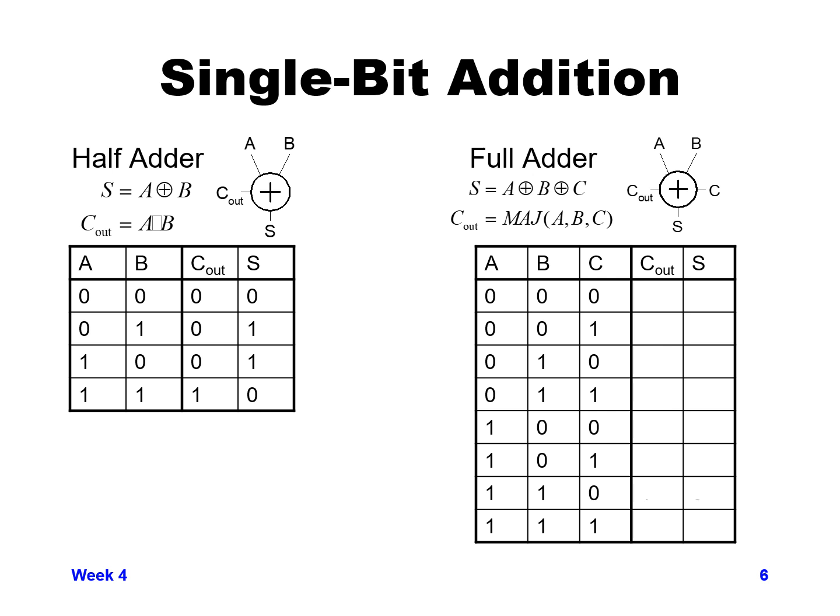In the case of 3 bits coming in, again, you'll only get a 1 if one of those inputs is a 1. Otherwise, if any 2 of them are 1, you'll get a 0. Or in the case of 3 bits of an XOR, if all 3 of them are 1, you'll also get a 1. Because in effect, with an XOR function with 3 inputs, you do an XOR of the first 2, and then with the result of that, you do an XOR with the third one.